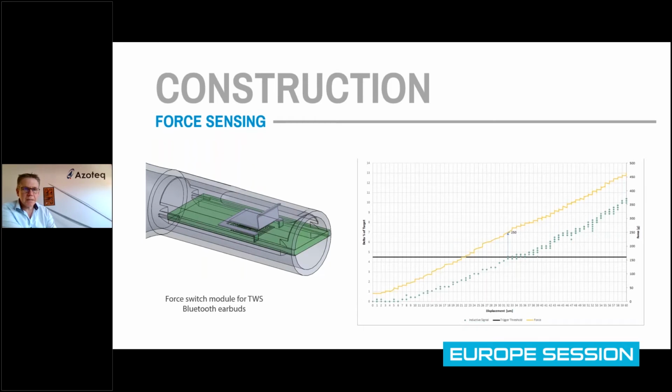From my picture on the screen, you see there's a metal spring hovering over the coil. If you move that metal spring closer to the coil, it is disturbing the electric field around the coil. That disturbance of the field is causing a change of inductance of the coil. And when the inductance of the coil changes, the current flowing through the coil changes, and we measure that. It's not a pure A to D technique, but it is a technique that is similar to an analog to digital converter.